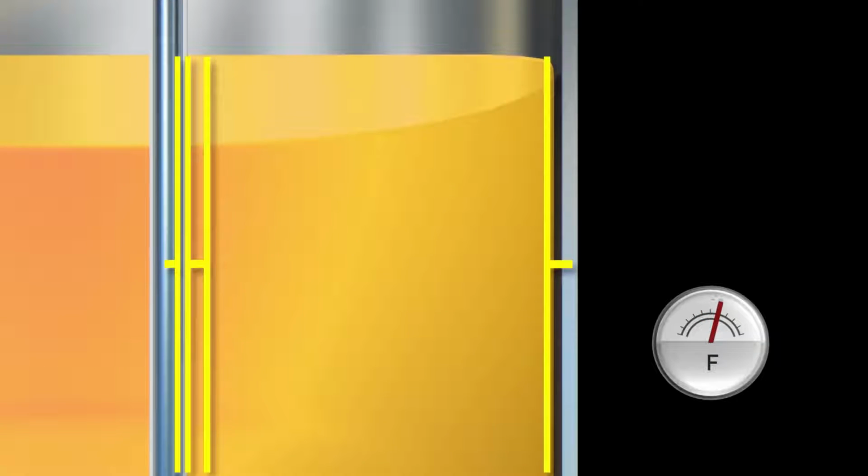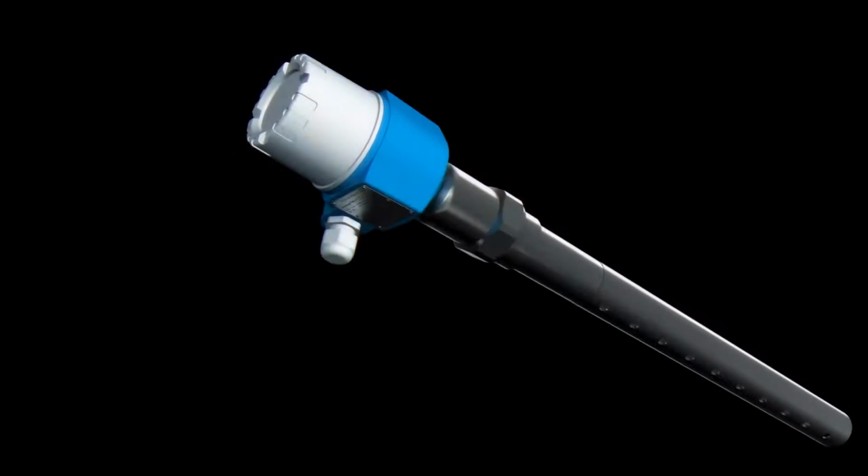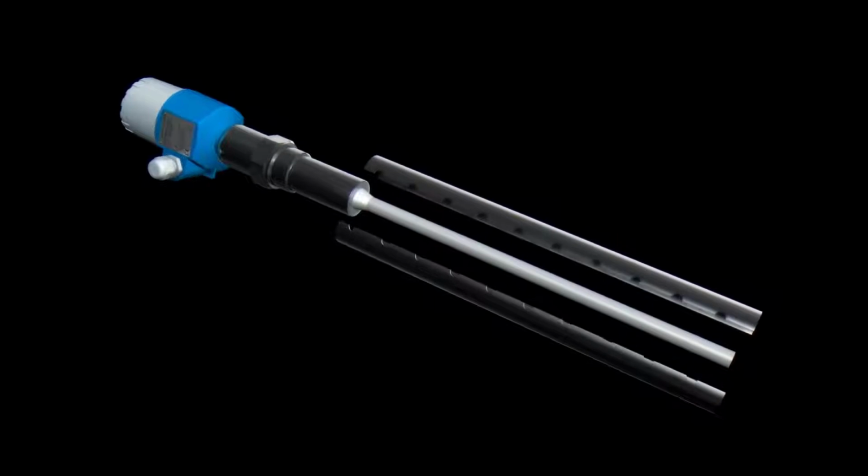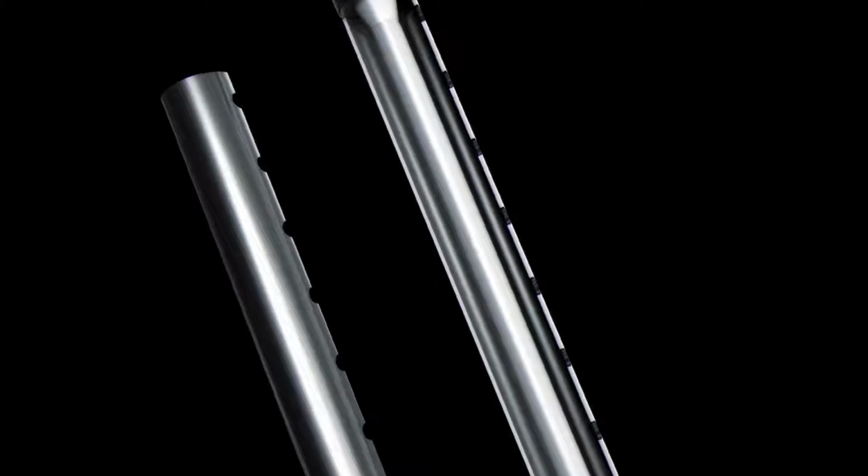The measured capacitance change is used to determine the level, and increases as the level rises due to the higher dielectric constants of the medium. The measurement thus depends on dielectric constant of the medium and the tank geometry. Therefore, ground tube probes are predominantly used, which represent a defined geometry and additionally increase the measurement effect by small plate distances.